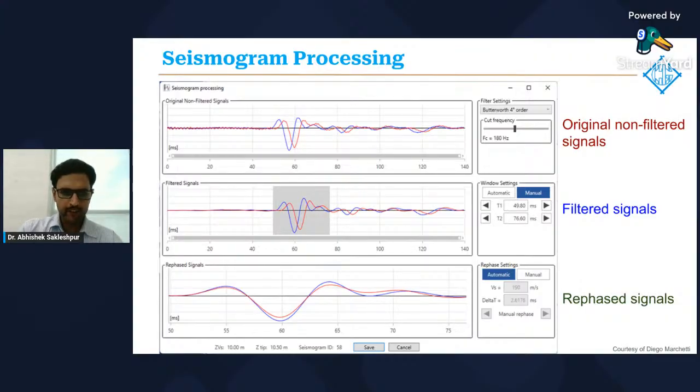And here we can see the test depth, which was 10.5 meters at which this test was performed. The shear wave velocity at this depth, as we can see here, is 190 meters per second, and the delay between the two waves is 2.6 milliseconds.